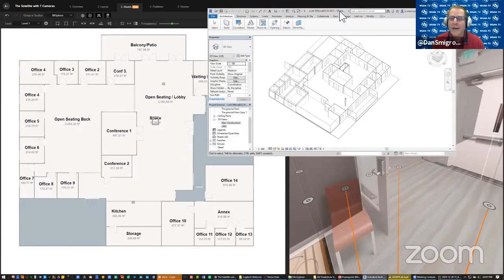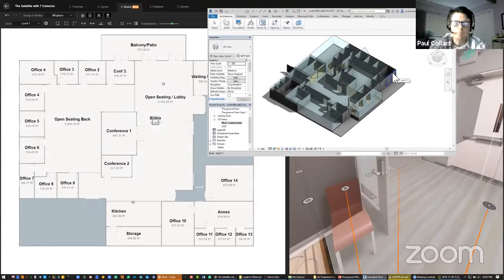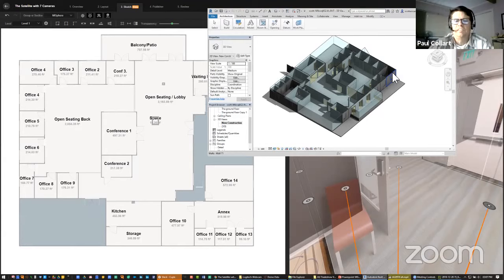So you are end-to-end turnkey to take it and then be able to export in a file format that's now actually usable, because the object file is really not usable in Revit or SketchUp. It's got to be converted somehow, some way. And we're dealing with the basic geometry of that space. So if you were to look up in the pano, you're seeing ceiling grids, you're seeing soffits and all that type of geometry. We're not meant to be creating that type of geometry. Correct. You're still going to rely on your BIM package to create that.